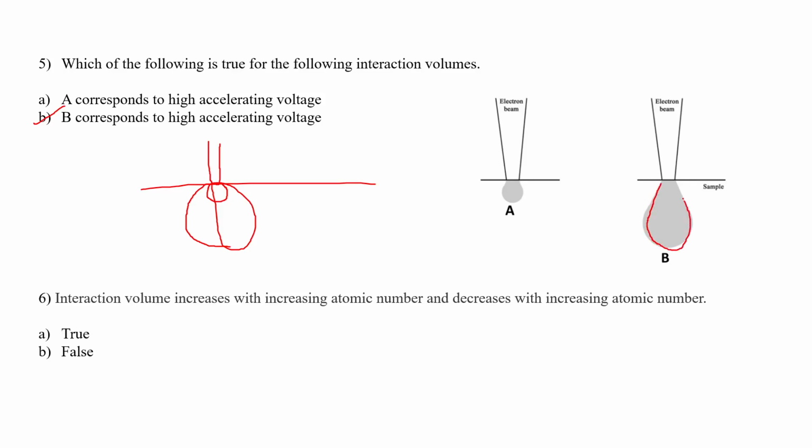This I will discuss in the next lecture. We didn't have enough time to discuss this in this lecture. Basically, when the electron beam falls on the specimen, it interacts with the specimen, and this interaction is given by the interaction volume. It is this pear shaped volume of the specimen, known as the interaction volume, from where all the electrons are emitted which we can detect. Depending upon the accelerating voltage, the higher the accelerating voltage, the higher will be the interaction volume.